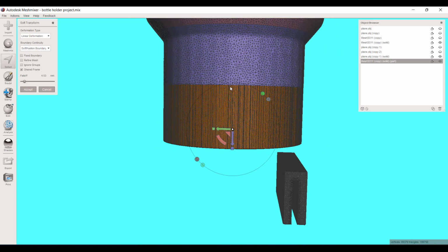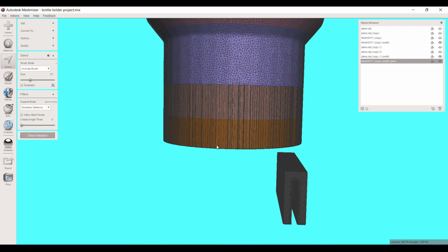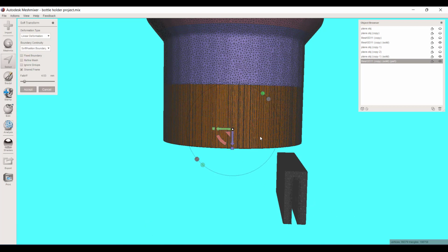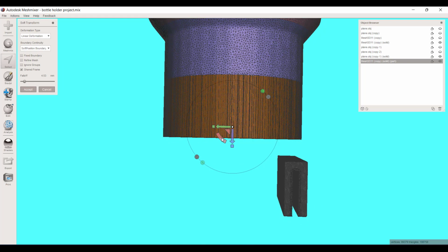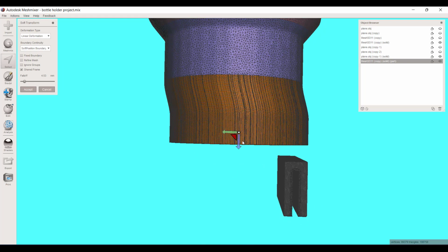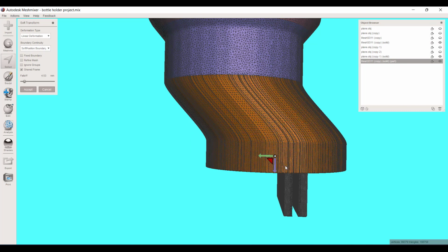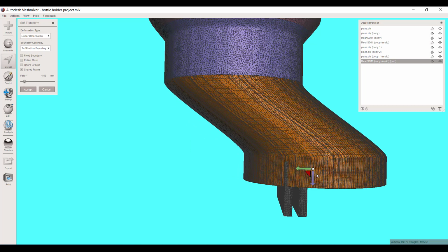If I had seen that my selection now for soft transform goes up into the purple, I would cancel it. I would scale my selection down, contract this ring a few more times until when I go to soft transform, it's going to leave this purple untouched in the selection. All right, but since that nailed it, let's just go with it. Soft transform. And now what I can do is pull this thing off and create my tapering funnel zone.